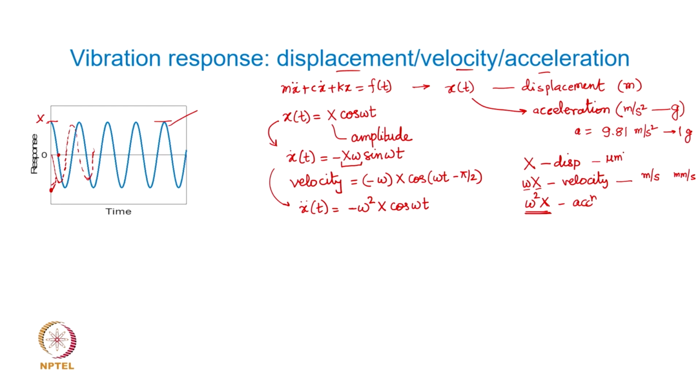Just to give you an example, our power plant steam turbine rotors typically will not have vibratory motion exceeding maybe about 50 microns or so. If it goes beyond 150 microns, the turbine is supposed to trip, and it is designed to trip when the lateral vibration amplitude goes beyond 100 microns, depending upon the capacity and the unit. Okay. So, typical vibratory displacements would be in micrometers, seldom exceeding a millimeter. Of course, there are certain applications where the amplitude of vibration will go beyond a millimeter level.